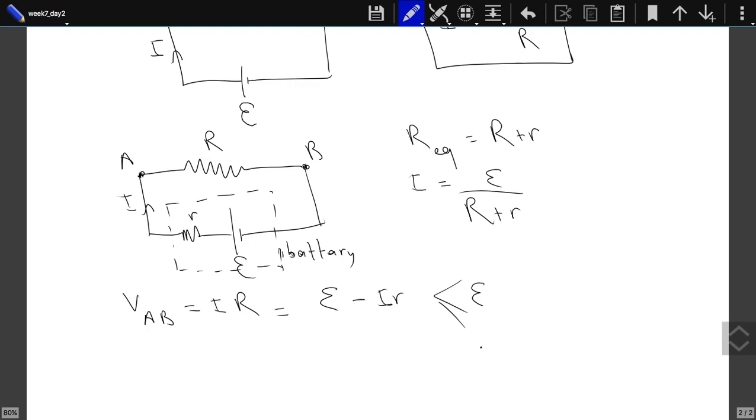So if for some reason your circuit needs at least 1 volt to work, you should get a battery that creates more than 1 volt, because due to the current running through your circuit, the potential difference across the terminals created by the battery will be less than its EMF. And the unit of EMF is also the volt, just like the potential difference.